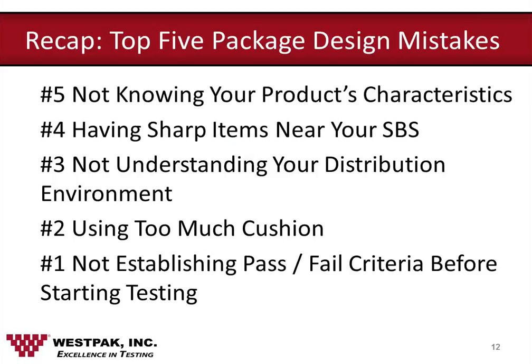Everybody for their time. We'll kind of go over a recap of all 5 of the mistakes we see people make when designing a package. Number 5 is not knowing your product's characteristics. Number 4 is having sharp items near your sterile barrier system. Number 3 is not understanding your distribution environment. Number 2 is using too much cushion. And the number one mistake we see people make is not establishing pass-fail criteria before starting testing.